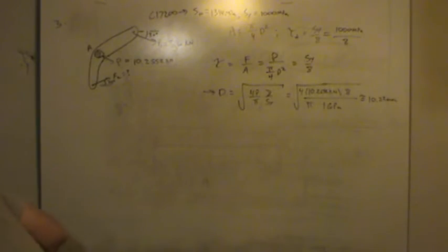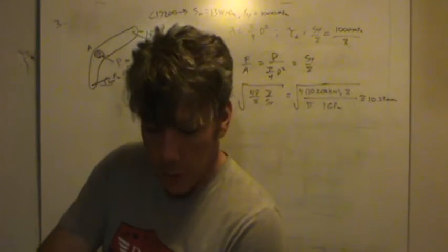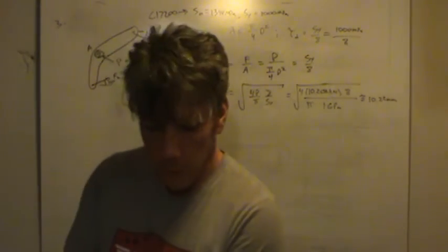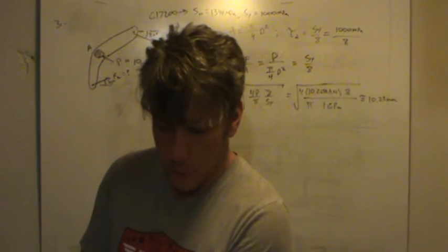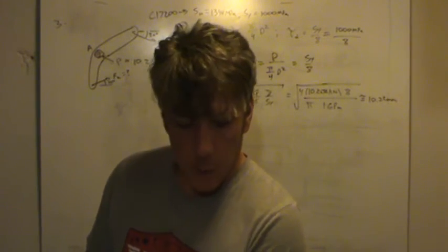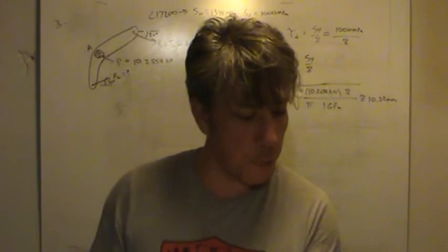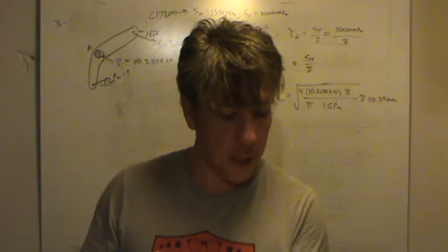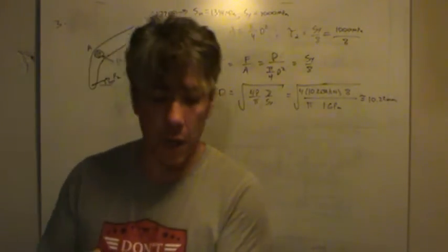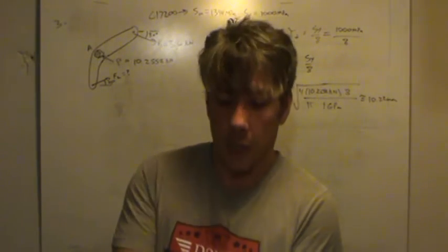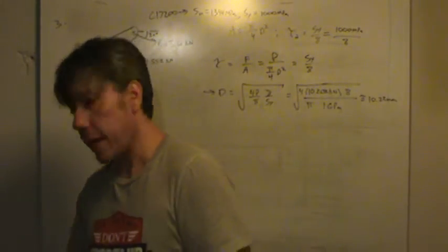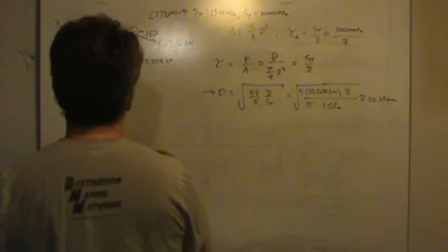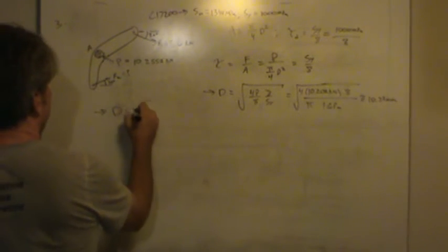And this is also a page you should probably bookmark, so let's go to it. Let's see. It's at the beginning of the appendix. The page number, here we are, is page 692. Table A-2, preferred basic sizes. They're first and second, that's their name. So the first preferred basic size above 10 is 12 millimeters. The second is 11, so I'm going to go with 12, mainly because I know that I probably would have trouble finding a pin that's 11 millimeters in diameter. So I went ahead and just said, well, specify then the diameter of the pin as 12 millimeters.